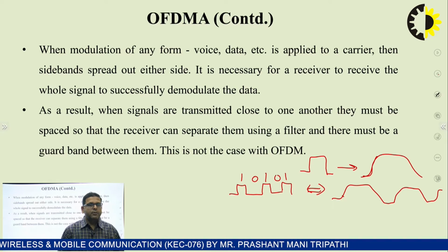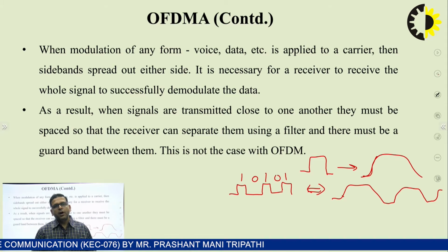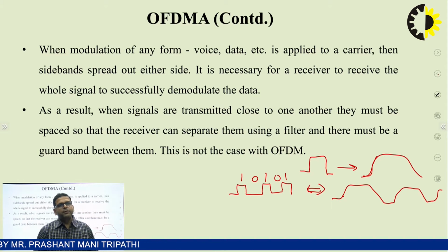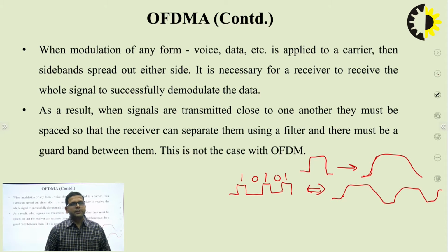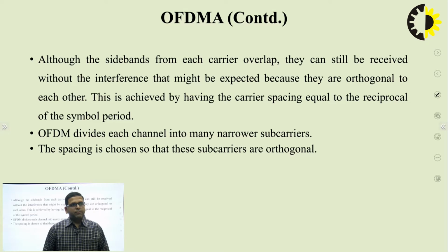And as we know, the presence of a guard band is also a wastage of bandwidth. All these problems are removed in the orthogonal frequency division multiple access technique. In orthogonal frequency division multiplexing, we divide each channel into narrow subcarriers.